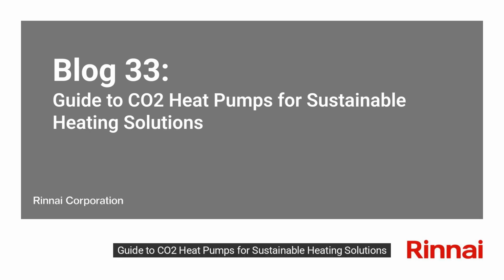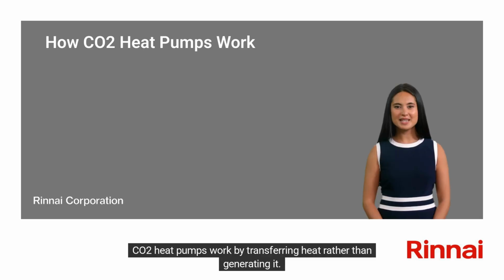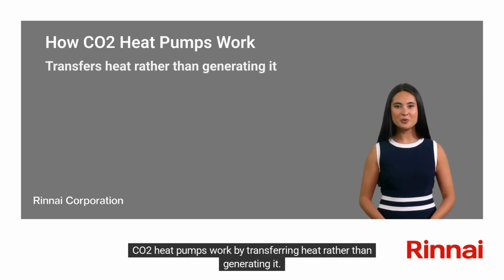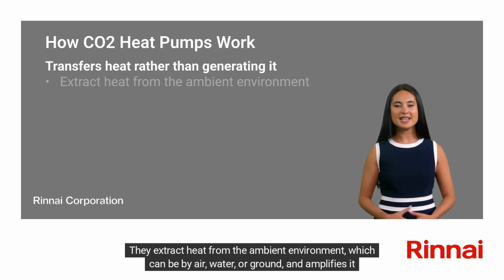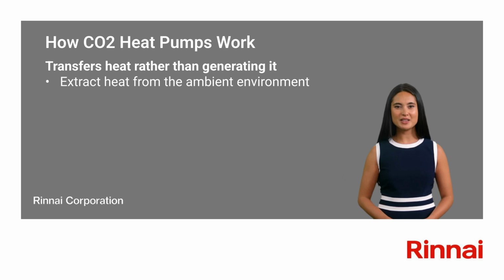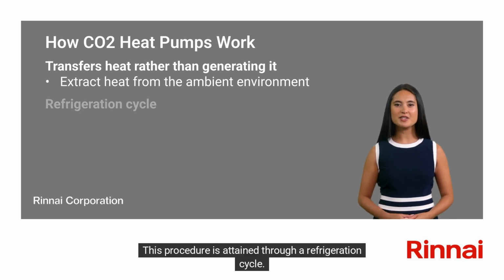Guide to CO2 heat pumps for sustainable heating solutions. CO2 heat pumps work by transferring heat rather than generating it. They extract heat from the ambient environment, which can be air, water, or ground, and amplify it for use in heating spaces. This procedure is attained through a refrigeration cycle.